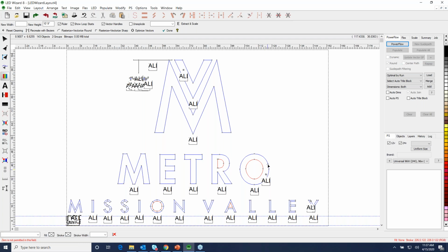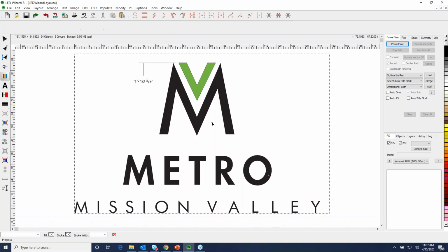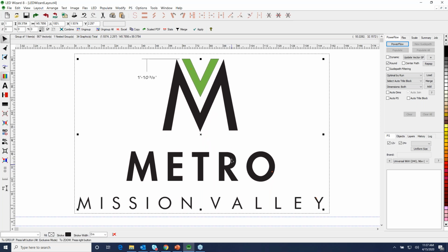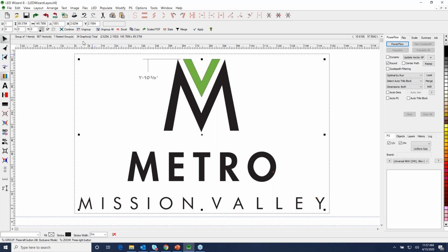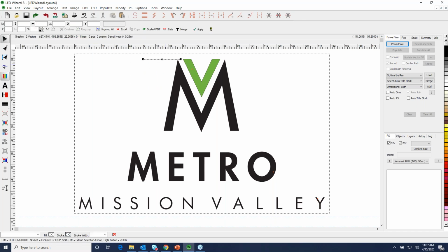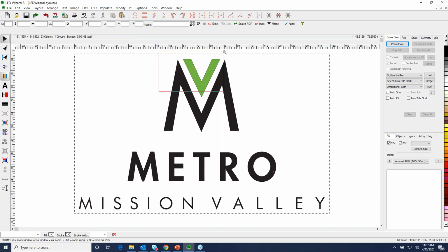And again, here's my points. If I want to switch those to arcs and lines, I can do that. Click on done. All right, and here's my object. Now, if you end up here and you have some extra stuff like this, I can ungroup. I'm doing U for ungroup, so I can just go like this and select this, get rid of this, and that's kind of maybe the standard way.